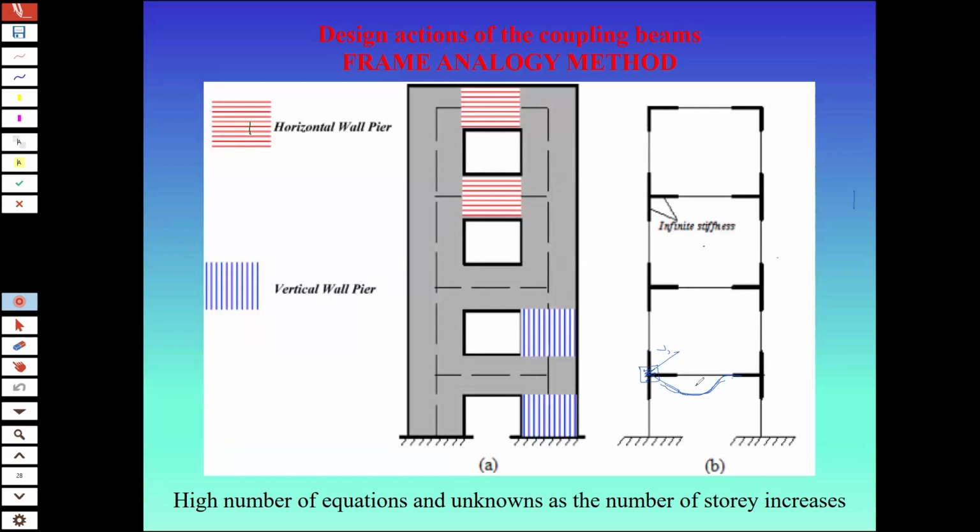So actually, also the coefficients, because when you have a beam like this and you apply a rotation phi here, you say that you have a moment of 4EJ over L here and 2EJ over L here. But this is not exactly the case. So you need also to work out your stiffness coefficients. Or you have to put rotations here, here, here, deflections there, which overcomplicates the thing.